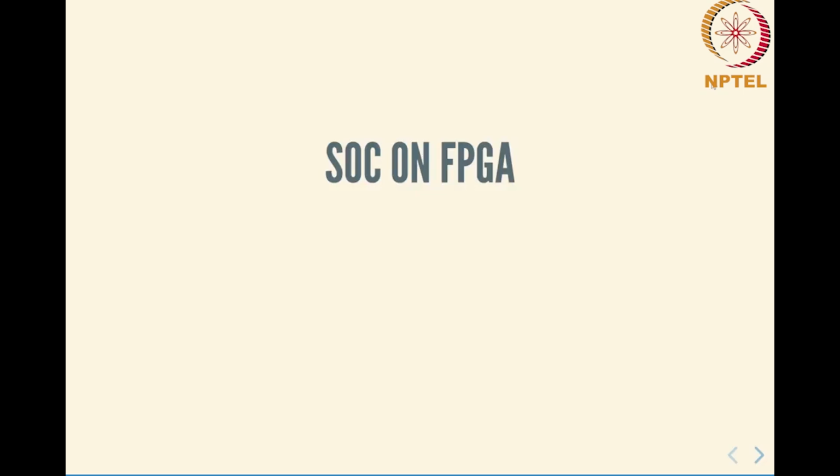Now, in principle, almost any arbitrary digital peripheral can be attached to this SoC. Digital, because certain things like A to D converters, that is the analog portion of that, cannot really be implemented on an FPGA because it does not have the analog interfaces. But anything that is digital logic can in principle be implemented in the fabric of the FPGA.